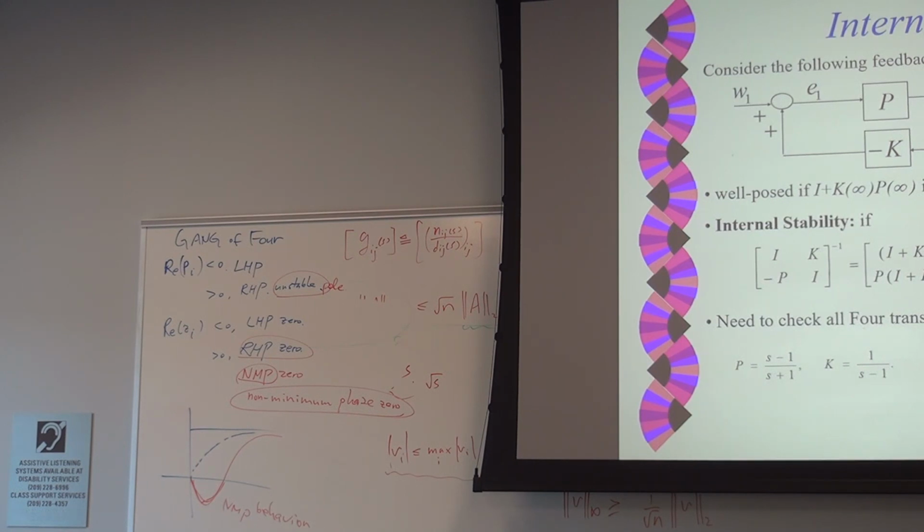But how can we check it in a simple way? Again, we return to the pole-zero cancellation in the right half plane. Here we clearly have 1 here. So for P SISO and K SISO, life is easier, right? But what if my P is a matrix, say 3 by 3, and K is also 3 by 3? In this case, it's really difficult to check, isn't it? Very difficult.